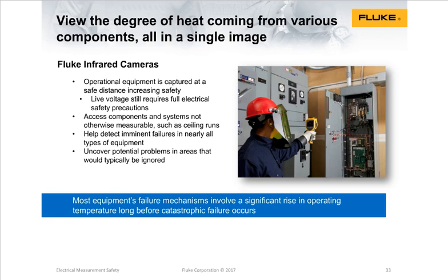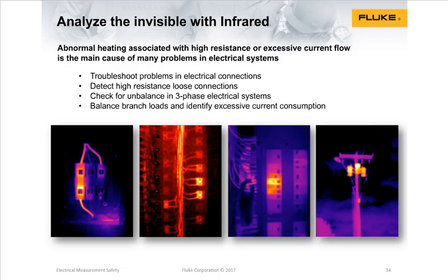And that's something that can be installed during a predictive maintenance or a type of PM where you're looking at a panel: you lock out, tag out, and you install the port. It's blast proof. They do have ratings on these ports, but you're allowed to look through the port with the window.